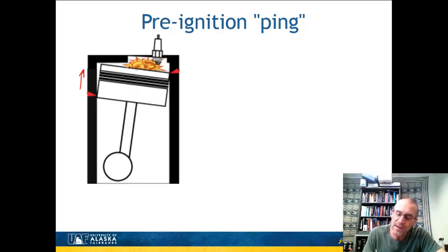And what that does, often the spark plug is a little bit offset. It causes the piston to twist a little bit because it's being pushed up, and then this explosion is causing hot gases to push down on it. This is pushing up. The piston turns to the side, and you have a couple contact points, which is the pinging noise that you hear.